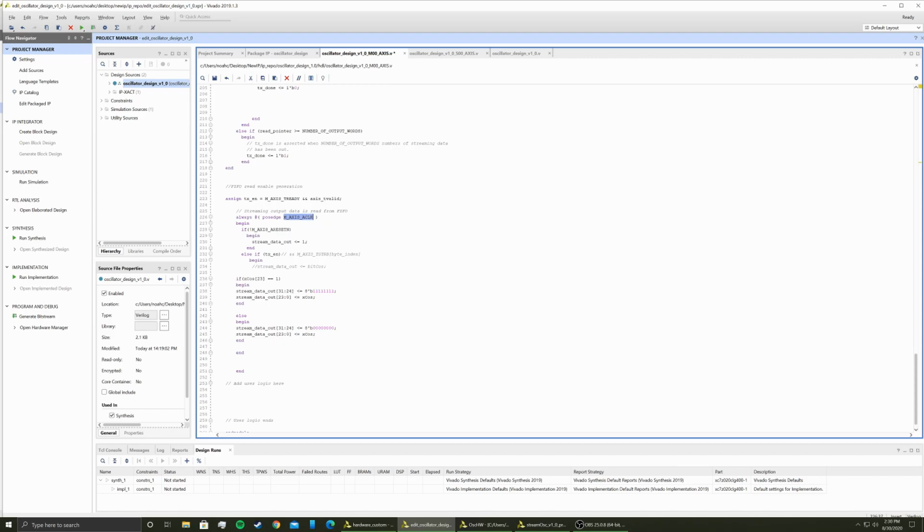So what I ended up doing was I said if my cosine leads with ones, because I have a 24-bit output and this is going to be 32-bit and I want to buffer it in so it has a sine signal. So what I did was I said if the top bit is 1, just buffer in the top 8 bits with ones and then just output my signal in the bottom bits, and otherwise, which means that the top bit of my 24-bit signal is 0, just buffer with zeros up top, and then the bottom 24 is just my signal. Essentially here you can just output whatever data you want into stream data out. Just remember that it is 32-bit by default. I do not know how to change it from a different signal, but this essentially allows you to output data from your module so that you can collect it later.